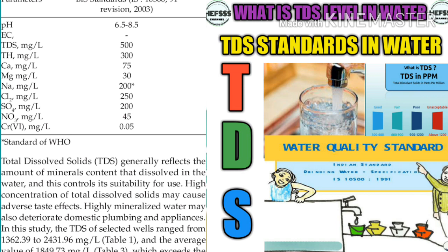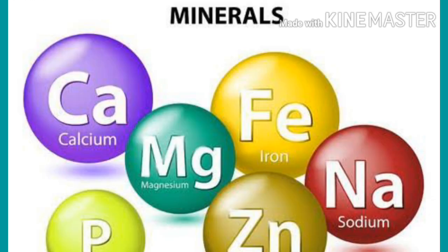So this is the entire picture of water TDS levels, how they are checked, and what the requirements are. The drinking water specification is also given clearly as per the IS 10500 standard, and bacteriological and virological requirements are also stated. IS 10500:2012 also gives general parameters concerning substances undesirable in excessive amounts.